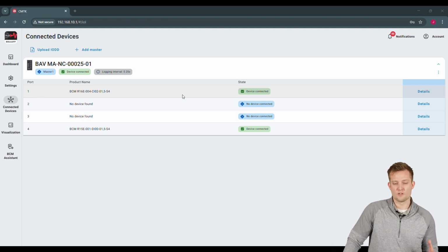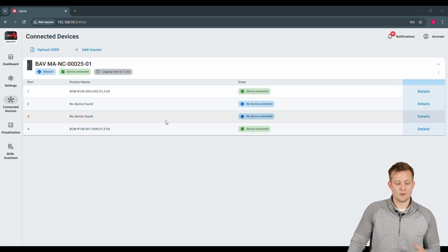So when we originally first started getting these types of sensors, a lot of people didn't know where to set their thresholds. So we would put a sensor on a motor like this, and we would just start monitoring what we considered a baseline. But from there, how do we know where to set our upper and lower limits? What's considered healthy vibration or bad vibration? That might lead to us potentially taking a motor out of service before it's fully ready for it to be repaired. So how do we look at that?